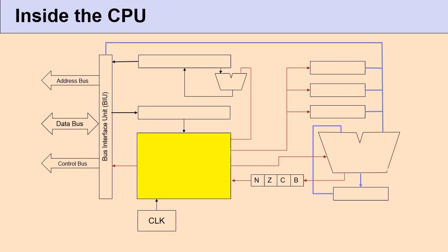Similarly, in our earlier lessons on the add operation, we knew that there should be multiple signals. For example, first you have to enable the inputs to the ALU, then command the ALU to carry out the operation, and finally get the output register to save that value. Likewise, there are multiple signals that need to be generated according to a predefined sequence that depends on the instruction itself. These timing signals and control signals are generated by the control unit. So it's like the nerve center of the CPU, which coordinates the operations with the other components in the CPU.